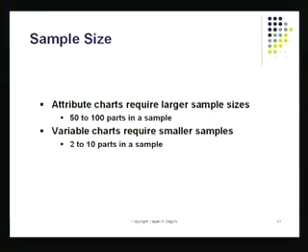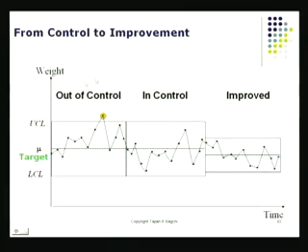If you're looking at the variables chart, what should be the size of your N, which is the subgroup of items that you decide to pick every time? So I collect so many data points and I average them out. I calculate one value of X bar and one value of R. How many data points do I need? It should be between 2 and 10. If you do that, it will be very easy to go to the table and find your quantities. And you could start with a process that is like this.